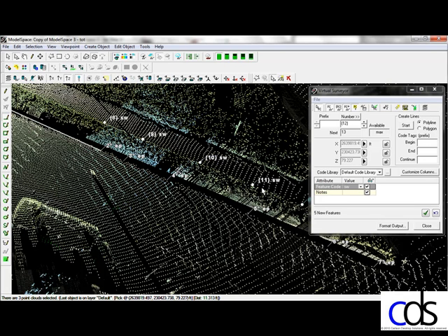If my focus is that I just want rough planimetric data, that's all I'm going to focus on. I don't have to worry about getting a good, detailed scan to pull all of this out. If my focus is on topography and I want to create a 2-foot contour map, I would collect the scan just like I would my topo with a total station or robot or GPS. Focus on what my end result is going to be.